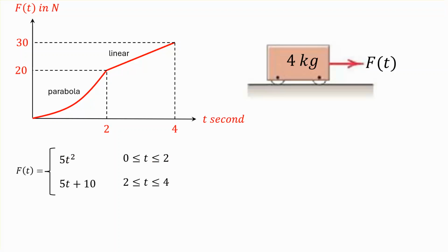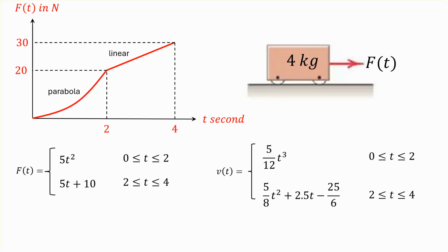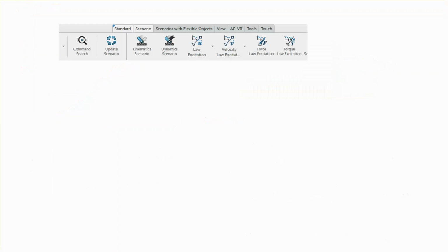But anyway, here is a force distribution, and based on elementary kinematics, actually integrating backwards, first of all finding the acceleration, you divide this by 4. Any of these, you get the acceleration during that time, and then you integrate it, you get the velocity distribution. So what I'm going to be checking is the 3D experience simulation for this problem against these numbers, against this distribution. If I match, then obviously I'm good. So quickly, I'm going to go through these slides, but you're going to see it as I create the model again, and I'll come back to it again.